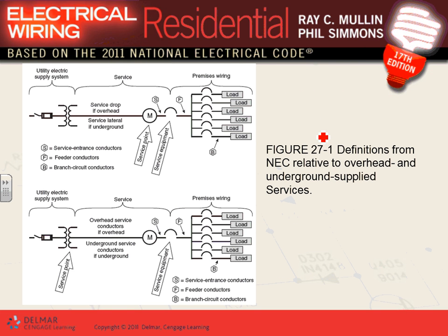Let me go directly into this one because this is probably one of the most important things. I want to highlight a few things, guys. I want to remind you that this here is your utility. Can you guys see that one? This is my service point, right at the meter. The utility will pull their conductors right into that meter. That's my service point. You can see the service drop overhead. These are the conductors coming from the utility into your meter.